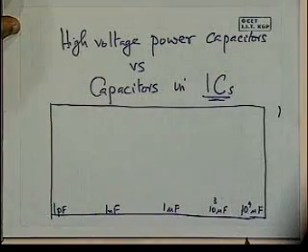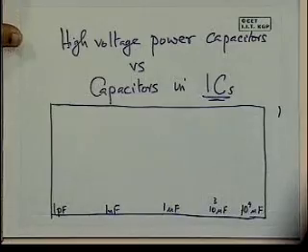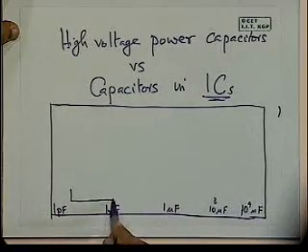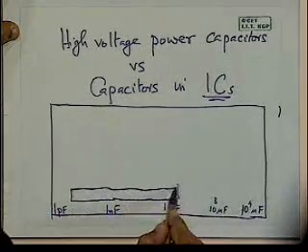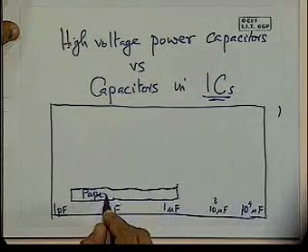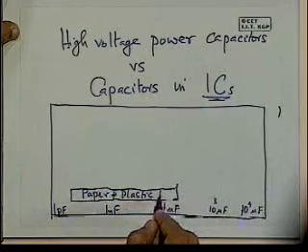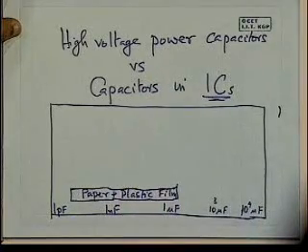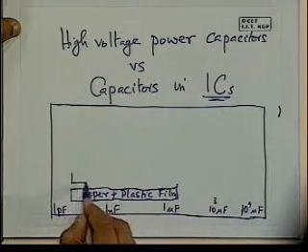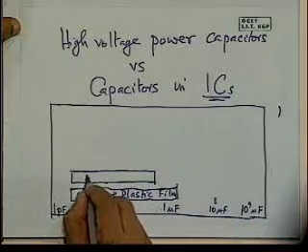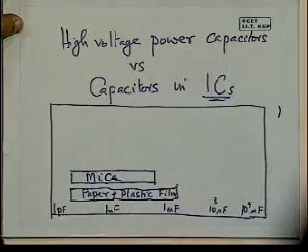What kind of capacitors or what kind of materials and designs would satisfy this requirement in terms of the achievable capacitance? When we look at it for using paper and plastic film, we can achieve somewhere from few picofarads to microfarad range. Paper, plastic films, you can do that. And if we look at mica, which is well known as a dielectric, it's an insulator, somewhat in the lower capacitance range, we have mica.